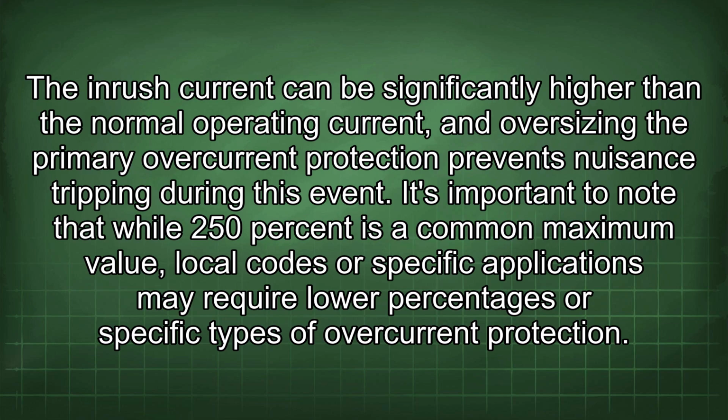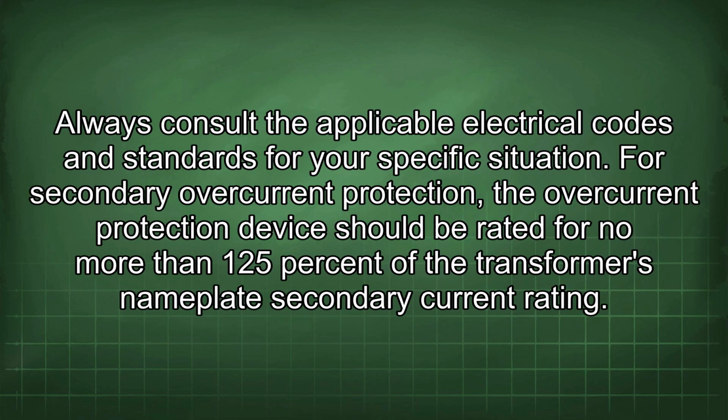tripping during this event. It's important to note that while 250% is a common maximum value, local codes or specific applications may require lower percentages or specific types of overcurrent protection. Always consult the applicable electrical codes and standards for your specific situation.